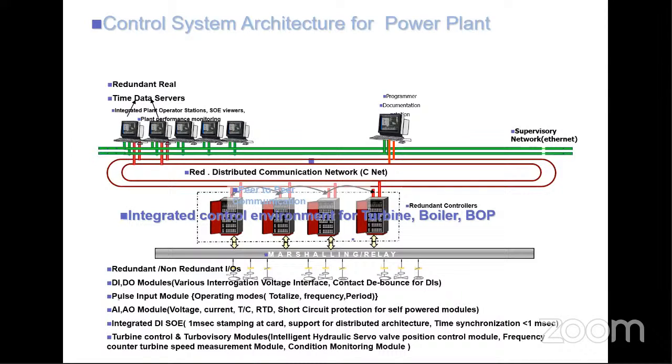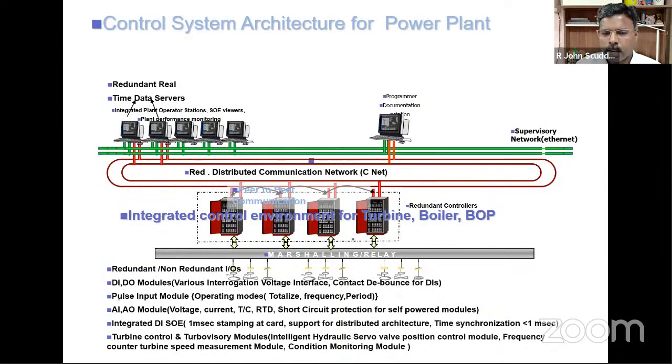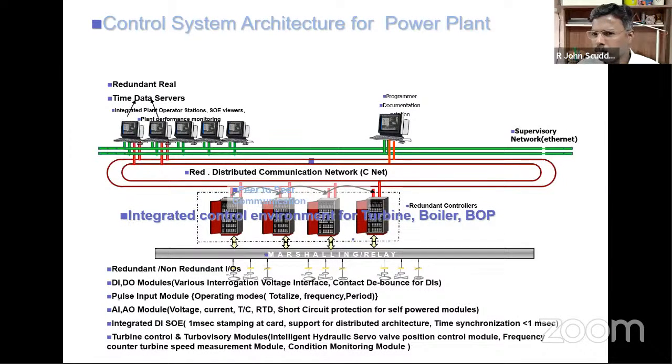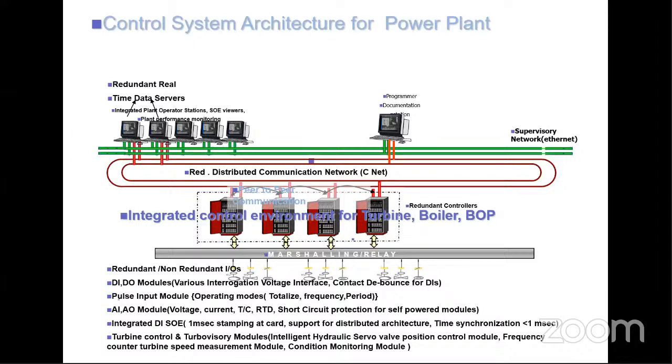The bidirectional communications, those are 4 to 20 communication, right, sir? Not only 4 to 20. In case of analog, it's 4 to 20. In case of digital, it will be 24 volts or 0 volts, depending on what input it is. Okay, if it is analog, it is different. So digital signals are 0 or 24 volts, and analog is 4 to 20. So we are converting to digital in the marshalling relay part also.